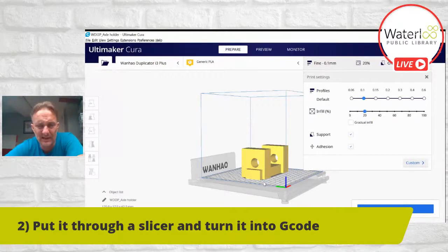A skirt, I believe, is the one where it's this extra plastic that just gets added in a layer spreading out from your 3D print. It's just to help make it stick to the platform. It's one of the common pitfalls with 3D printing. When the physical printer is printing, the bed that it prints onto is a little bit warm. It's a little bit heated to help keep the plastic from shrinking. So what will happen is it will squirt out this plastic.